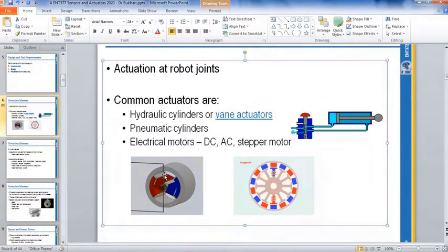Compared to a DC motor, although you use PWM to turn the motor, the same concept as a stepper motor, pulse width modulation, a DC motor will have a problem like drift. So if you say stop, the motor still has a drift error, it overshoots. So that one is the DC motor.